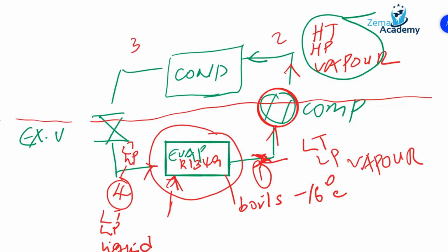By passing it through the condenser, you're sinking that high temperature and high pressure. Here you will have a secondary circuit to remove the heat from the condenser. Again, we will look at whether you're using air or water to remove the heat. And that's how a condenser is classified, as either an air-cooled or water-cooled condenser.